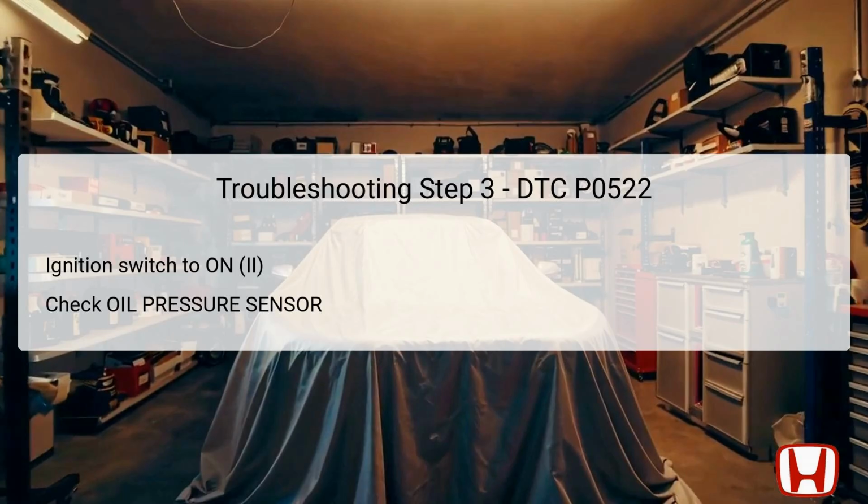The critical point here is to determine if the voltage falls at or below the 0.18 volts threshold. If it does, you should proceed to step 8. If the voltage exceeds this limit, it indicates a malfunction within the circuit that could involve faulty wiring or connections. Both the immediate and historical data readings are vital for diagnosing the issue accurately and ensuring that the repair is effective.